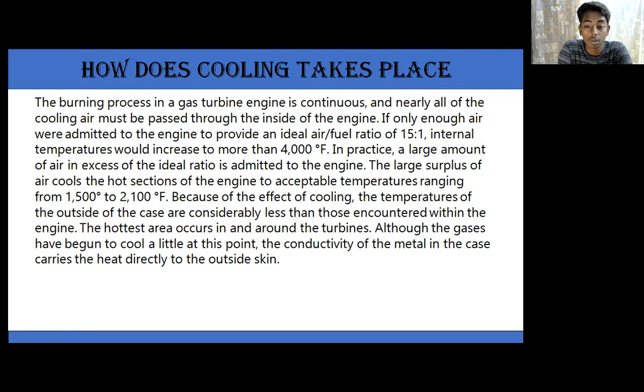Because of the effect of cooling, the temperatures of the outside of the case are considerably less than those encountered within the engine. The hottest area occurs in and around the turbines. Although the gases have begun to cool a little at this point, the conductivity of the metal in the case carries the heat directly to the outside skin.